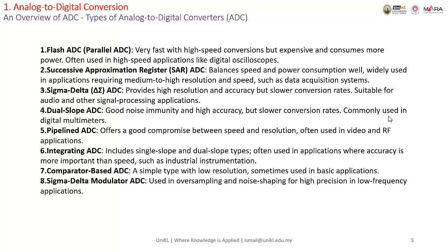This one's block diagram is a bit different from the successive approximation. It works somewhat like charging a capacitor, and then taking the time taken for the charging and discharging of the voltage across the capacitor.